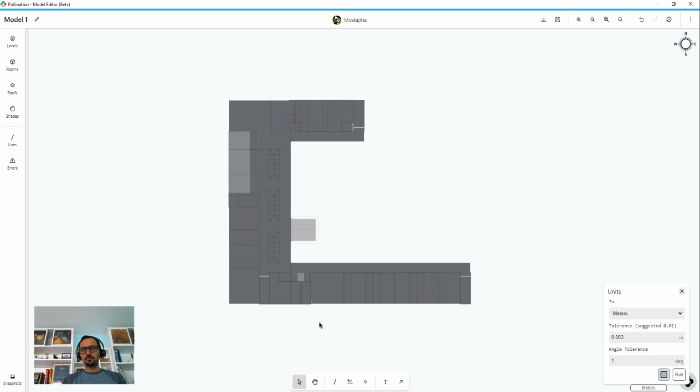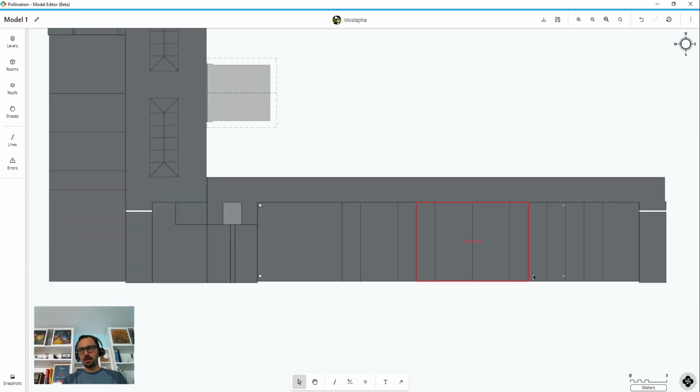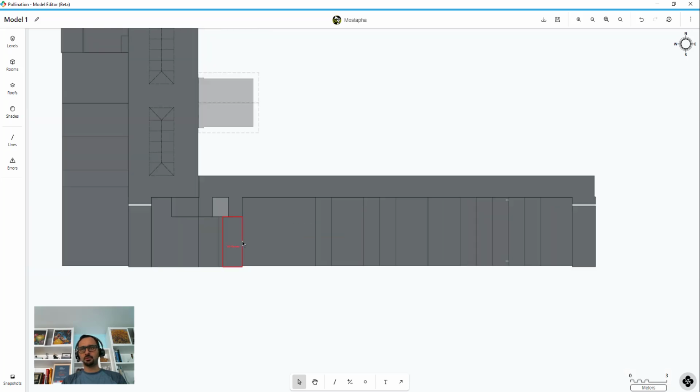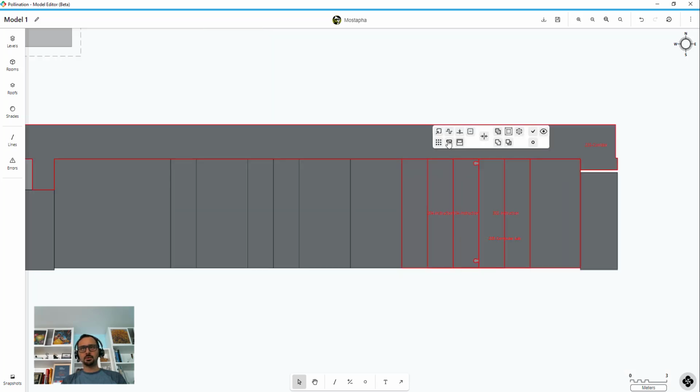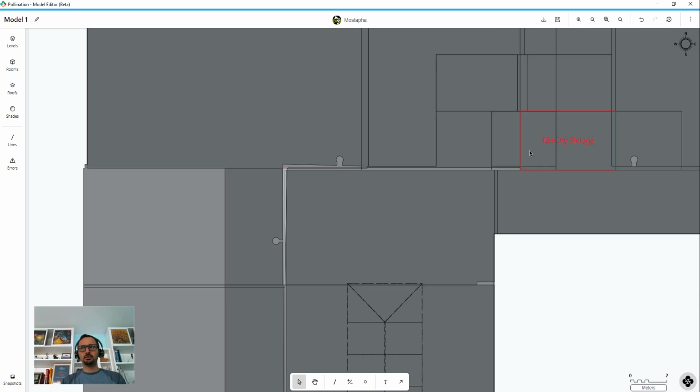Now, it's not that easy, right? There will be columns usually next to the walls, edges of the room. For these, there's a different command to use. I just select this, and the command is remove short segments. This one removes every segment that's smaller than this distance. So if I put 40 centimeters, that should work fine. So this one is removed. I'm going to also select this one and use the same command to remove. We have some here too, right?